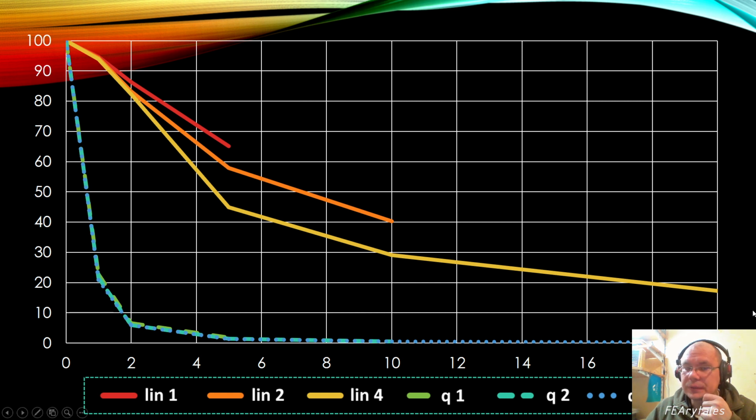It's a huge difference. And this is why in most cases for frequency, for modal analysis, for linear static, for buckling, engineers don't like linear tetra elements, because you need a very, very fine mesh with very small element size, with a very big number of elements, and with a very huge amount of resources and matrix size to calculate adequate behavior.